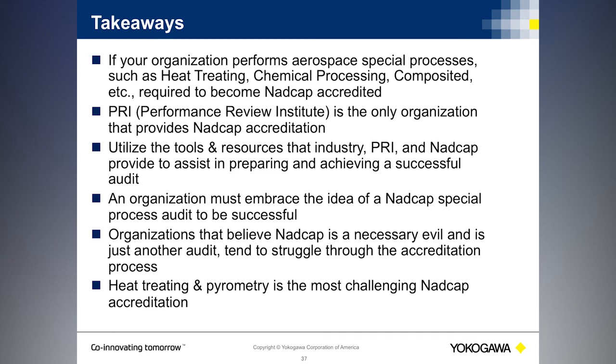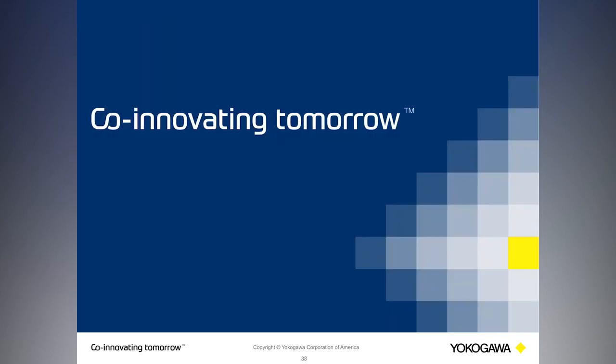You have to review your thermal processing equipment for its capabilities to meet the applicable processing, testing, and pyrometry requirements. You need to perform robust internal audits of your system to drill down on any possible holes within your processing capabilities. And once you've captured all those steps, it would be time to go ahead and schedule your audit and see if you're ready for the PRI experience.